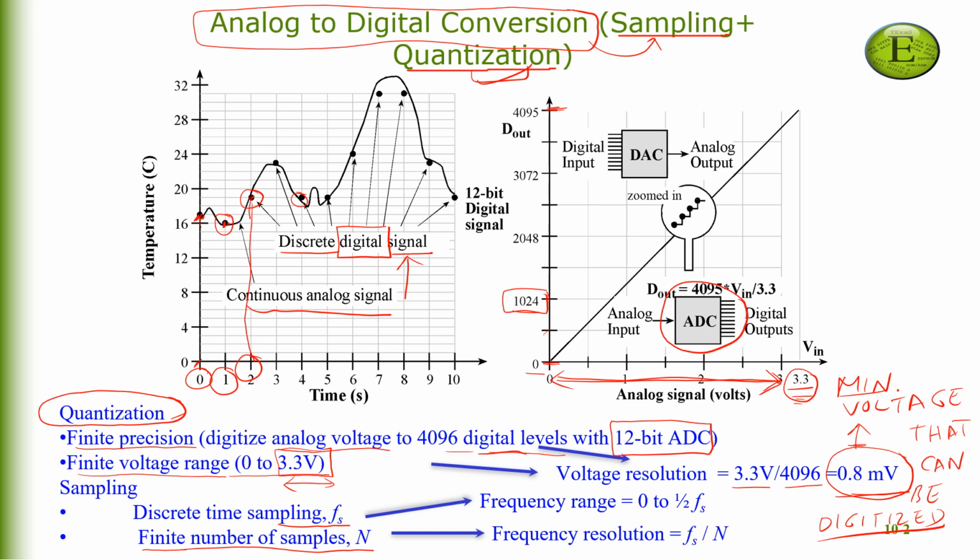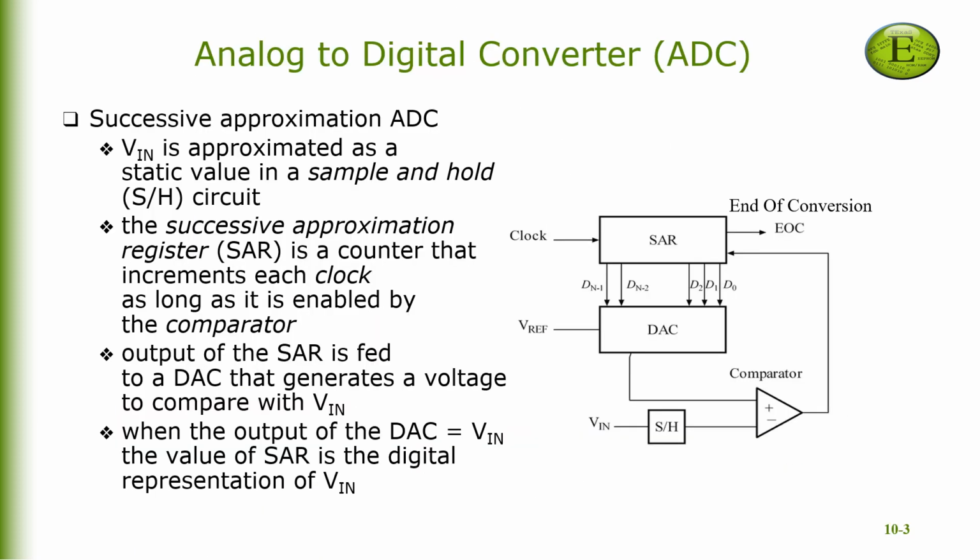You can also interface a higher resolution or a high-speed ADC depending upon your application, but we shall restrict our attention to the 12-bit ADC that is an internal hardware module of the microcontroller. Now we're not going to discuss different types of analog to digital converters in detail. In fact, we are going to restrict our attention to a brief discussion of a special type of ADC that is located inside your microcontroller. It works according to the principle of the successive approximation ADC.